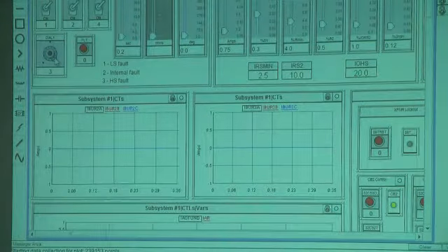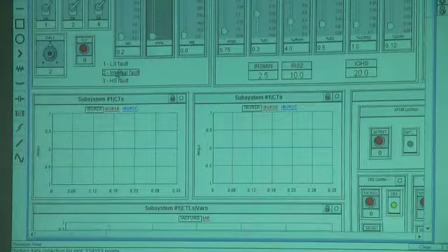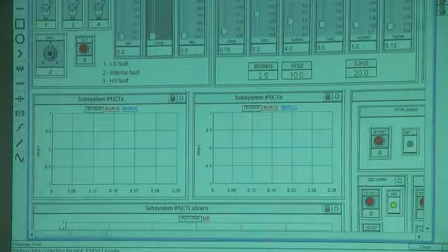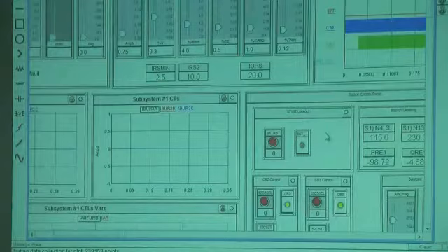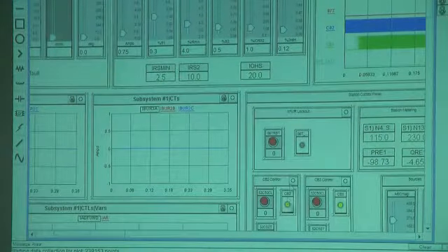I've got a dial here, so if I put it into position 2, we're going to have a 3-phase internal fault, and our 86 lockout relay should operate. These breakers should open.